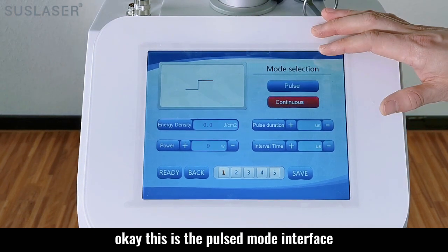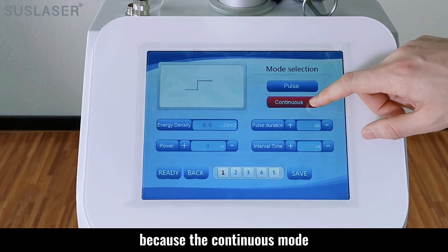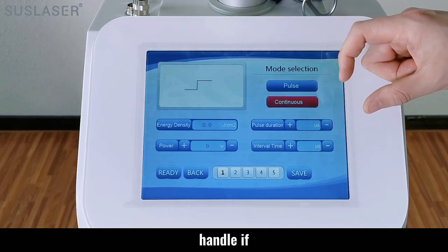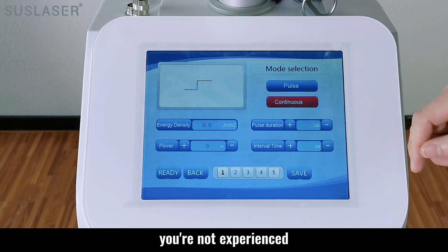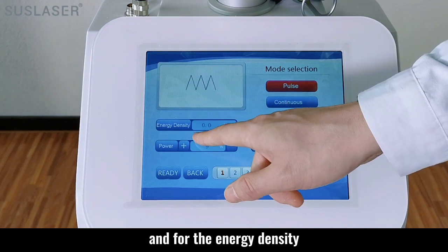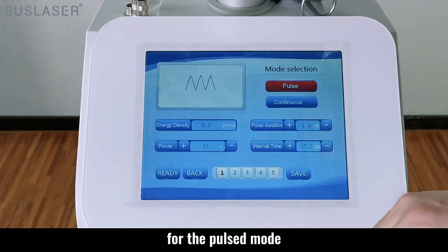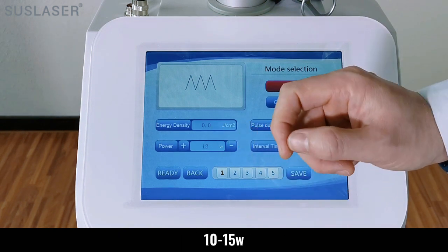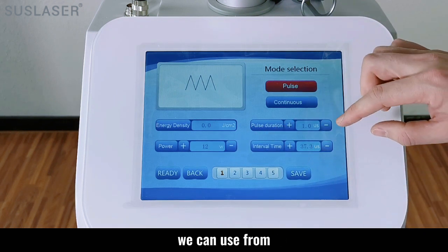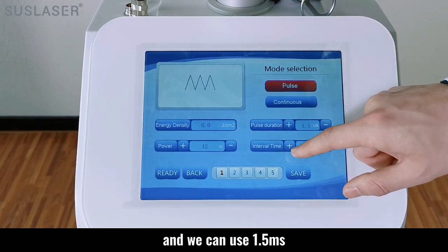Okay, this is the pulse mode tip. Normally we use the pulse mode because the continuous mode will be way too strong and really hard to handle if you are not experienced. So we will use the pulse mode, and for the energy density we can choose the power. For the pulse mode, the power we can use from 10 to 15. We can use 12. And the pulse duration we can use from 1 to 3.0. And we can use 1.5.